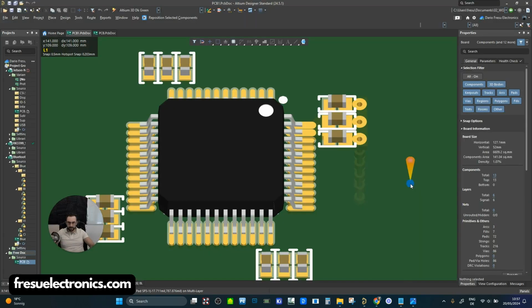Okay, so now the question is how we're going to calculate how many capacitors we need in our circuit to guarantee this target impedance. First of all, we have to calculate the target impedance that we are allowed to have in our system. So we need to really understand what is the target impedance that I can have for my system.